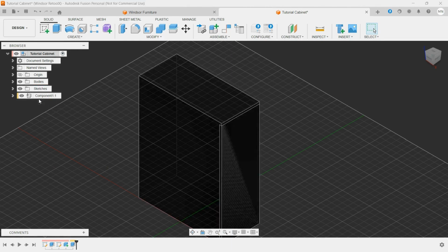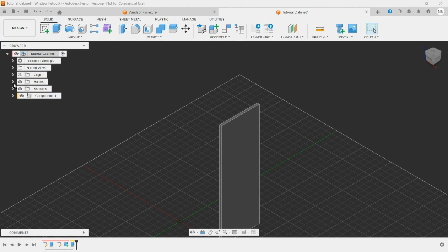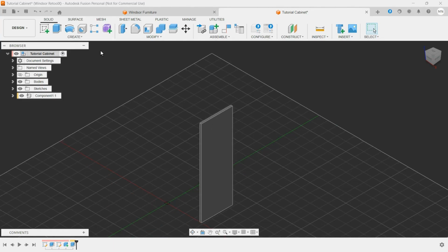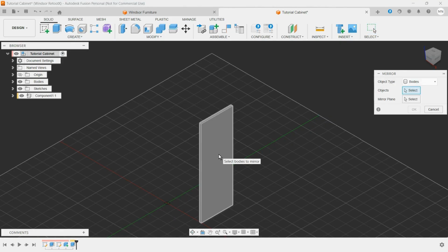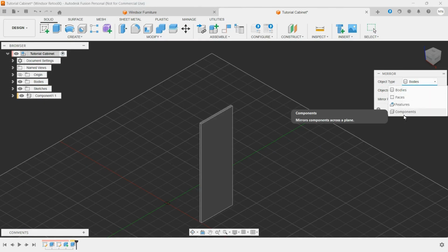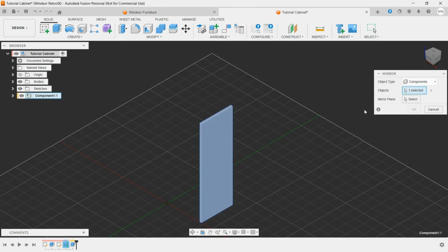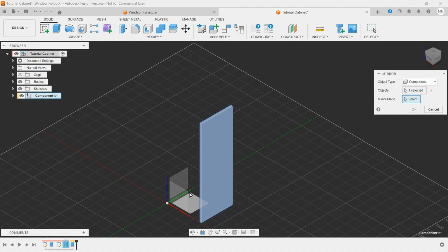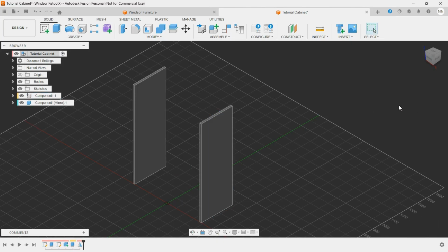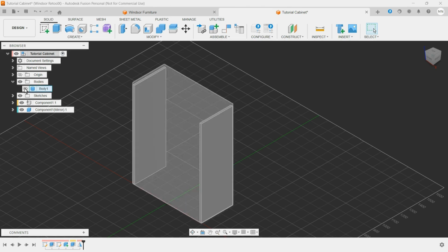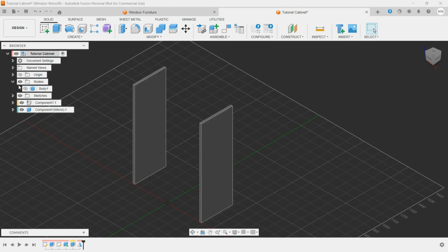So that's going to extrude that face towards the inside, and we have that space for our top face. You see the first original body, we can hide it, and we are going to use it only to check. Okay, and we're going to use now the create drop down, and we're going to make a mirror of our side component, because the opposite side is going to be exactly the same. So once we select mirror plane, we can select, I think, our YZ plane. And if we show our original body or transparent body, we see that it's all working good.